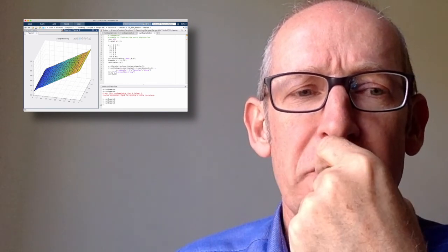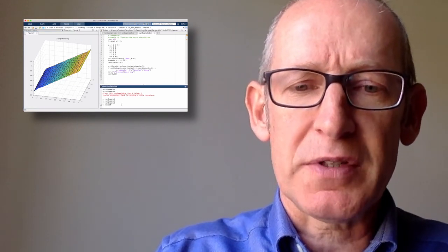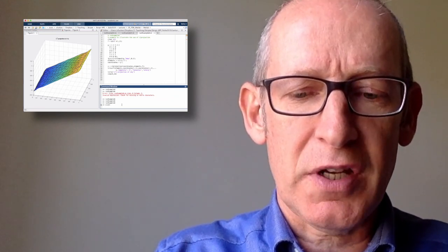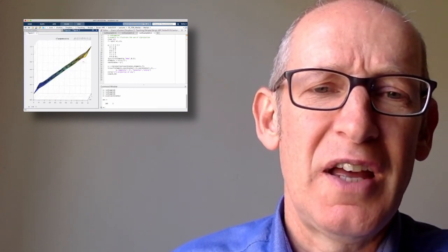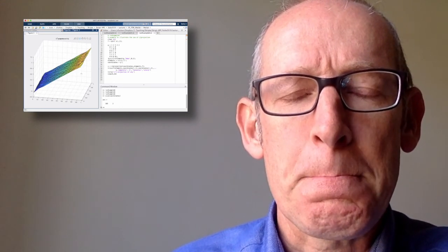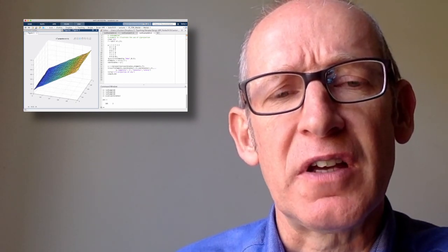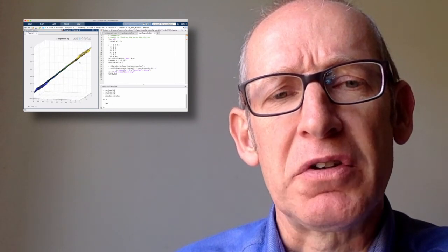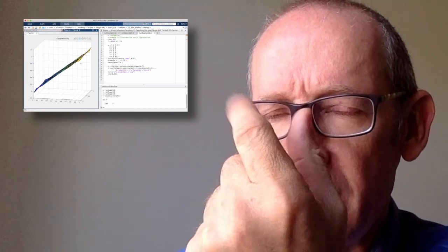We solve the linear system of equations, but the size is size of elements, size of coordinates, which gives just 185 unknowns, and these wrinkles, or these oscillations, are too much for just rounding errors from solving the linear system of equations. What could be the reason for these errors? Not the mass matrix, not solving the linear system.